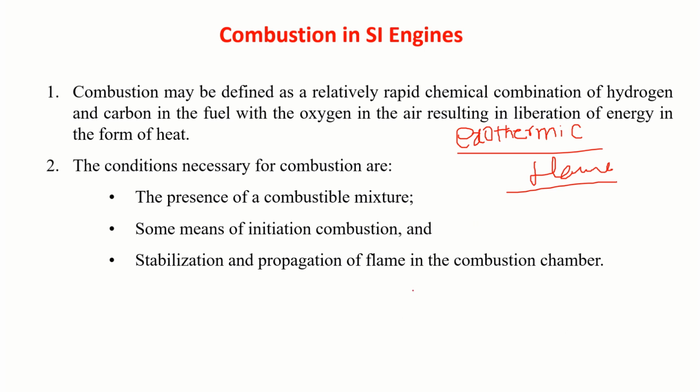For combustion to occur, you require a combustible mixture, let's say fuel and air, in proper proportion. That is very important. Then once you bring this fuel and air in contact, it will not ignite by itself, so you require an ignition source.